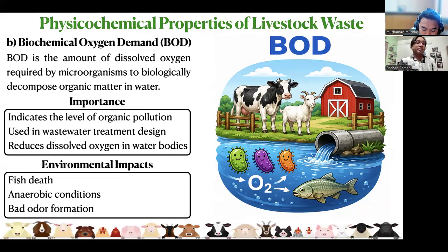It also has some environmental impact. In case of BOD, oxygen is used by the microorganisms for the breakdown of the organic matter. It ultimately causes anaerobic conditions inside the wastewater, which causes the death of fishes and other aquatic organisms.